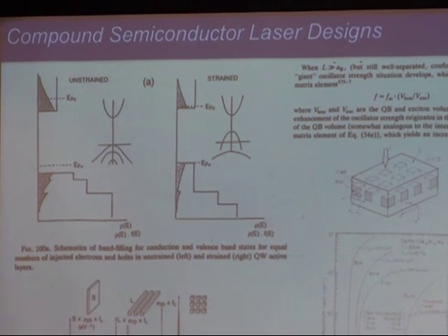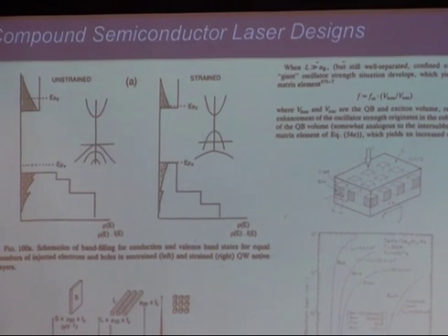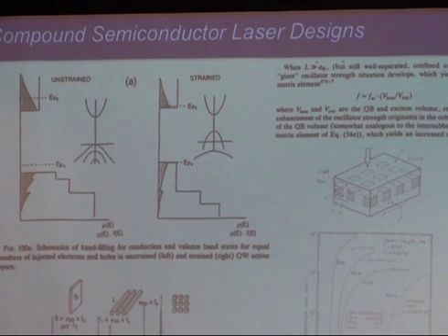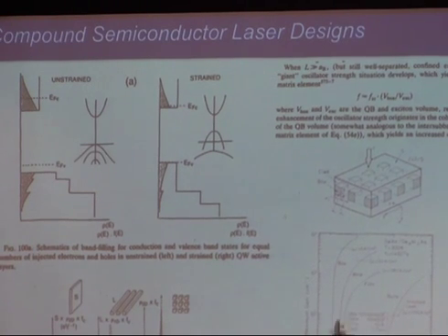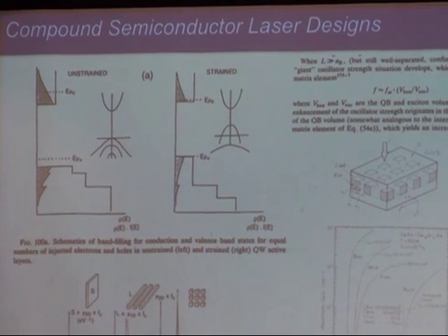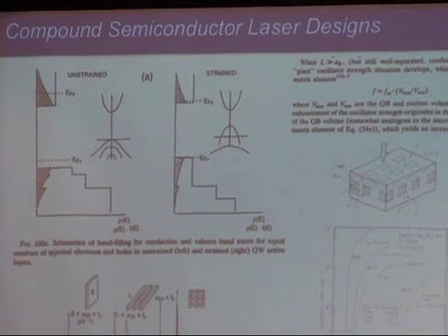So that's one of the advances in strain quantum well lasers, and they are obviously very useful, used today in telecom wavelengths, and being looked at carefully also for visible and such. This picture is not very clear, but essentially what you can see is if you reduce the density of states, going from quantum wells to quantum wires to quantum dots, your peaks really get sharper. It goes higher and higher. Again, from a very simple paper calculation, described in Weisbuch and Winter. Sorry for this picture, but what's showing here is the lasing gain with threshold current: here's a bulk material, here's a double heterostructure, here's quantum wells, here's quantum dots. So you can get into lasing at a lower and lower threshold injection current as you go to lower dimensions.